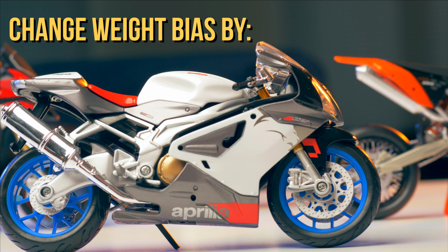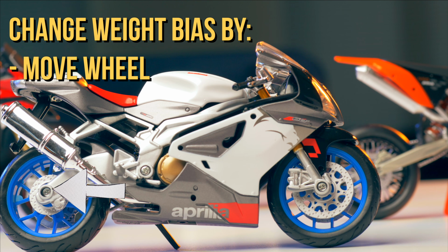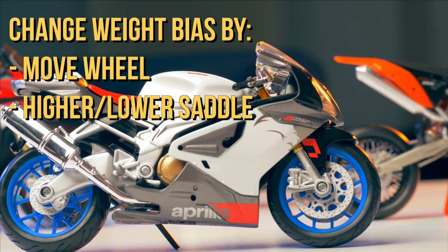On sport bikes, the weight bias can be altered by moving the rear wheel fore aft. Moving the wheel rearward will result in more weight on the front wheel. Padding under the saddle can also help move the rider forward on the bike.